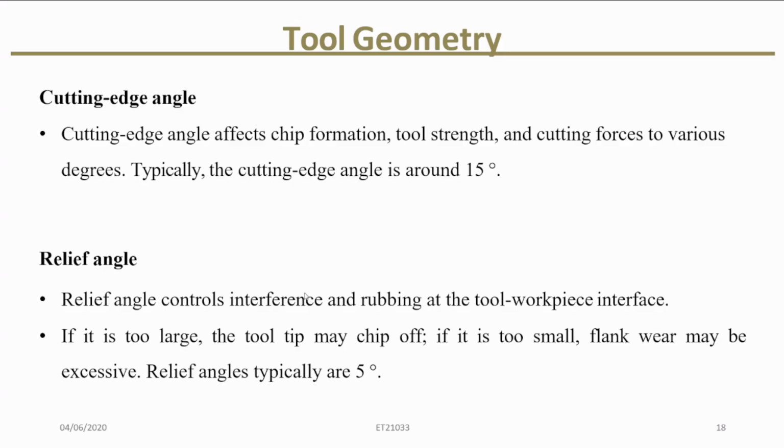I already told you if the relief angle is too small, there is flank wear and heat. If it is too large, the tip becomes fragile and can chip. The typical starting point of the relief angle we can mention as about 5 degrees.